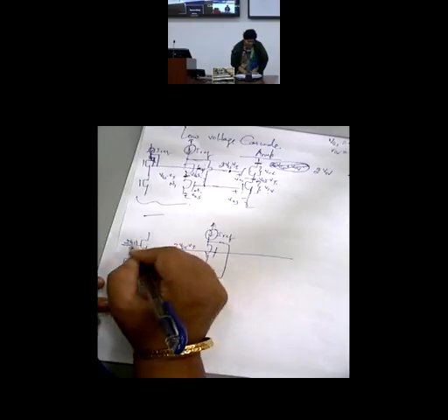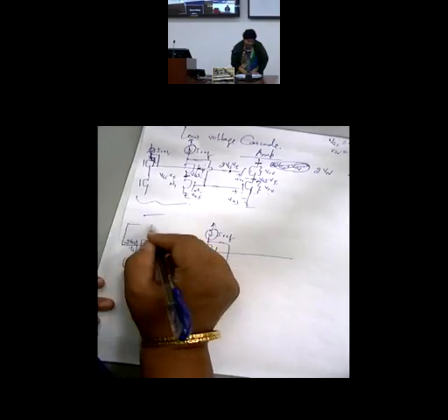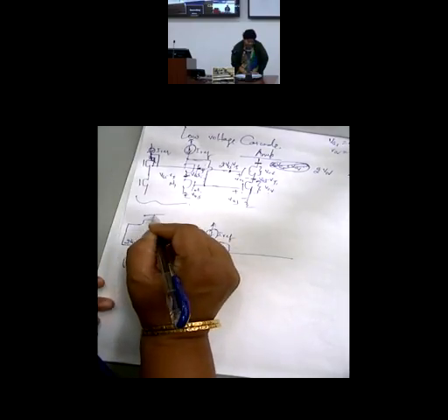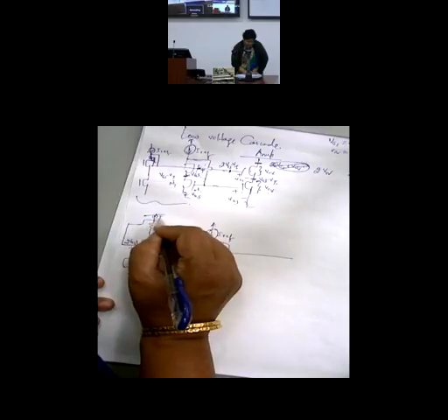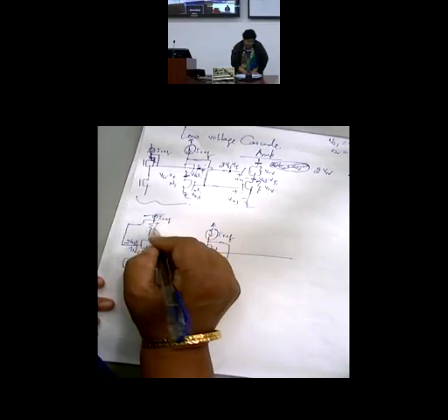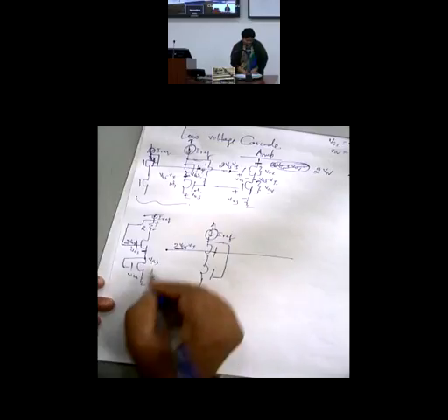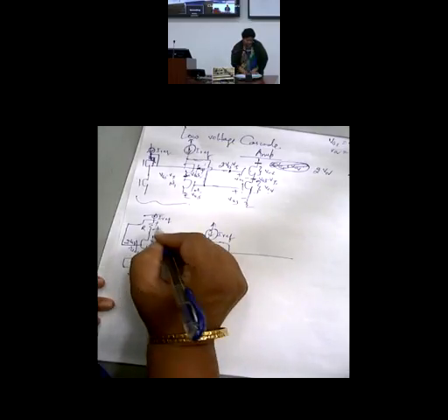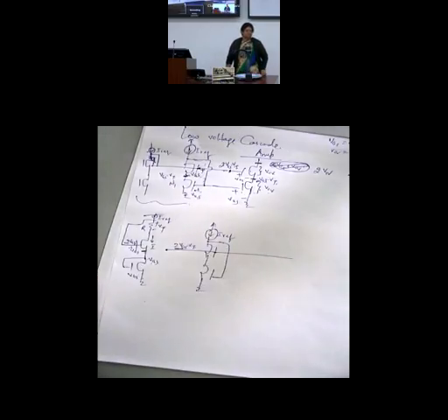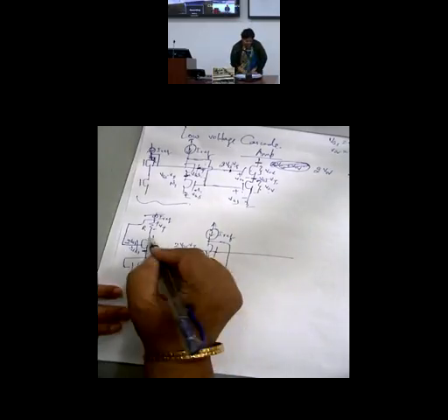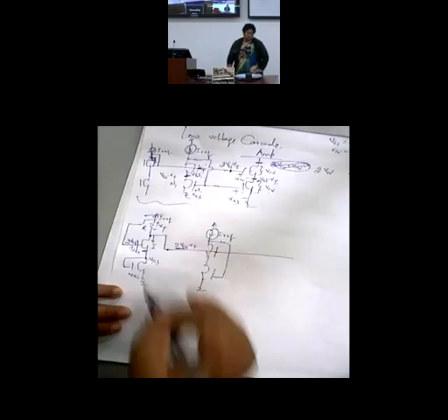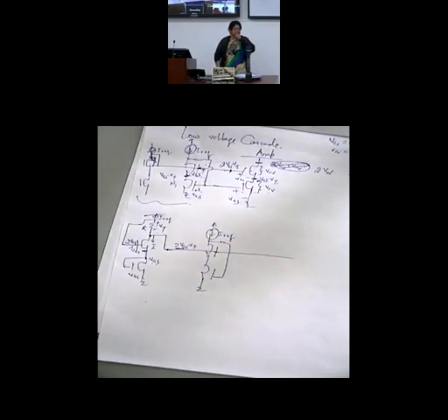So what I do is that I take it up, have a resistor here, and then this is IREF. And I configure the value of R such that for the given I through this arm, the potential drop is 1 VT. So that means this node automatically comes to 2 VGS minus VT.